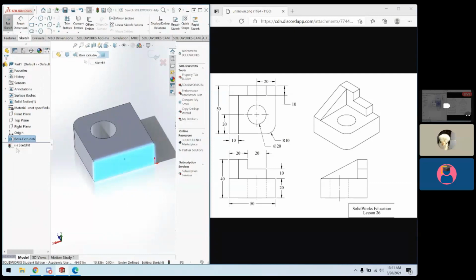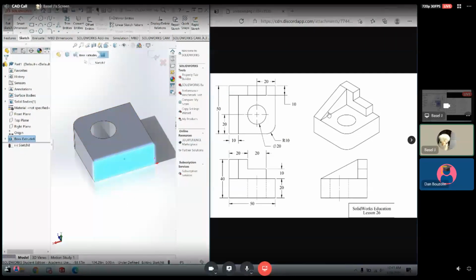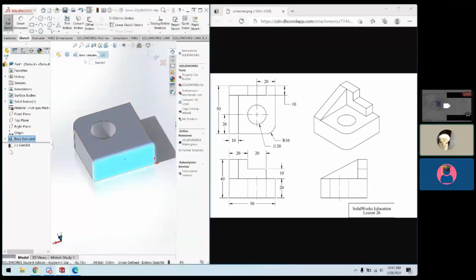click on the manager tree where it says sketch 8, and you're going to see this traffic light sign. This traffic light sign is basically saying it's still in progress. It needs to... what was the word? I forgot. Rebuild. Yeah, it needs to rebuild. So there's the sign over here as well. What rebuild basically means is, say you change the dimension, but the model itself did not update. You can press the rebuild button and it will update the model.